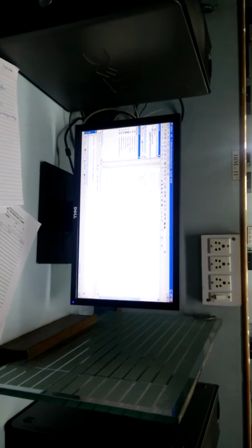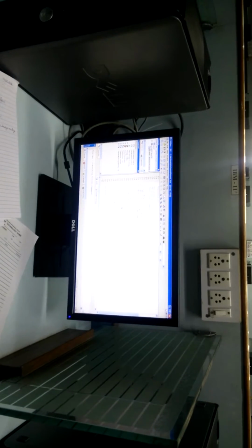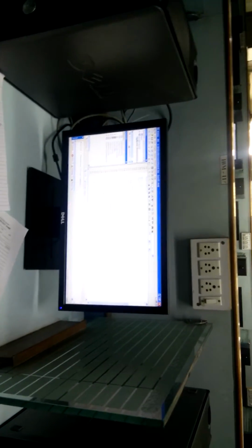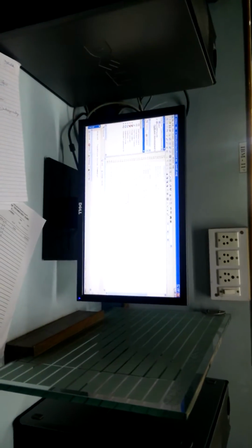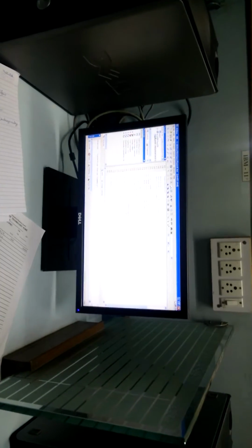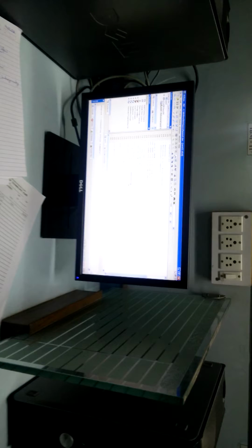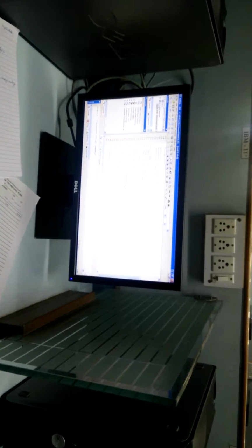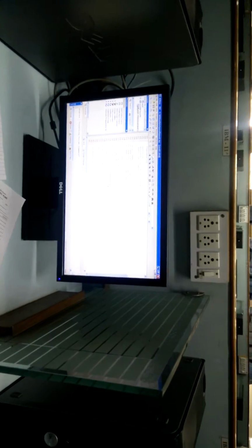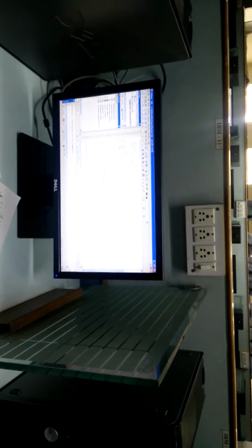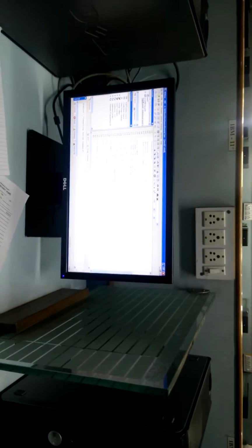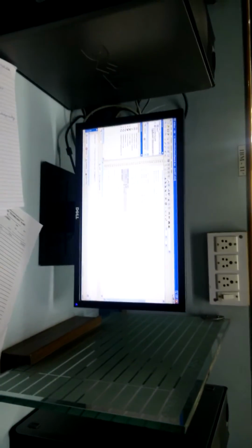Entity AND2, with ports a and b of mode in, and this is the STD_LOGIC. Now this STD_LOGIC is a scalar quantity. If it is a vector, then the notation is STD_LOGIC_VECTOR with some dimension, 3 down to 0, 2 down to 0. So this is the entity.